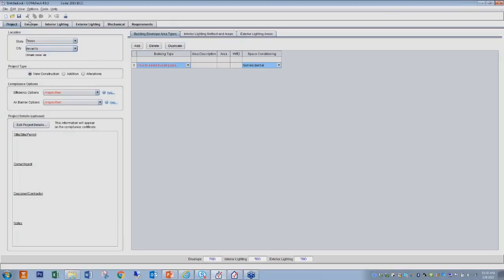All right, so same applies. I got this file menu at the top. First thing I want to make sure is that I have the applicable code on. And in here, where I talked about standard 90.1, that's a choice in there, but we're going to keep it on 2015 for right now. I don't think I'll have time to even look at 90.1 2013, but you could play around with that later if you wanted to. But you can't mix and match. I highly suggest you don't enter an entire project using 2015 and then switch codes, because there are different provisions, there's different assembly types, things will change, and you're having to fix things. So if you're going to start a project, don't start switching between the codes.